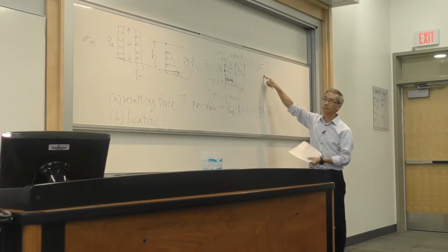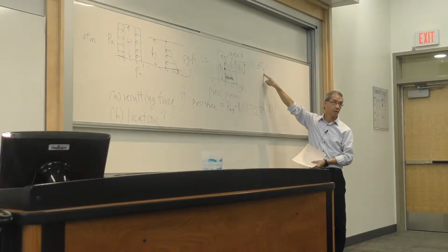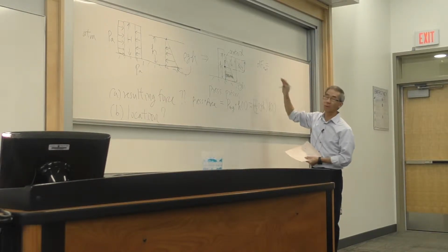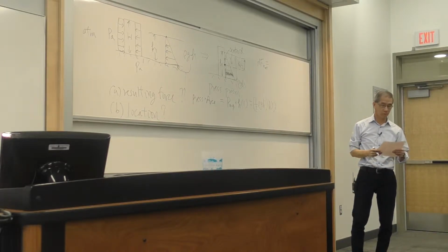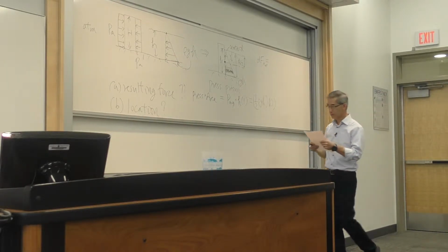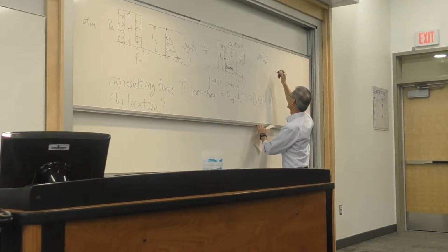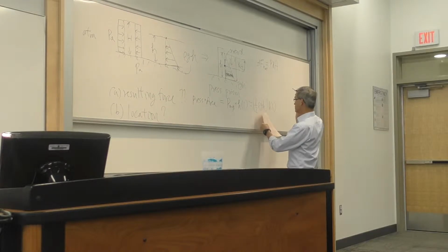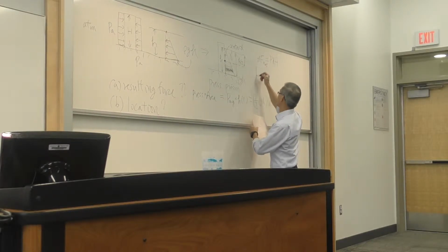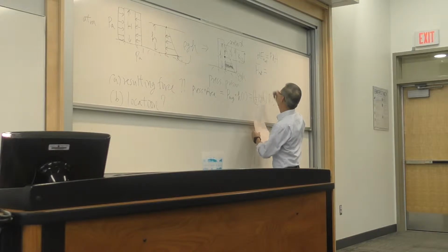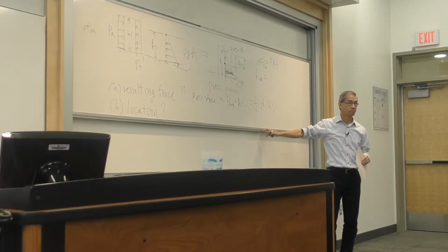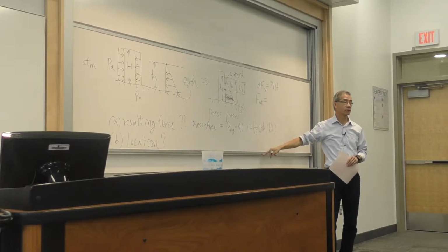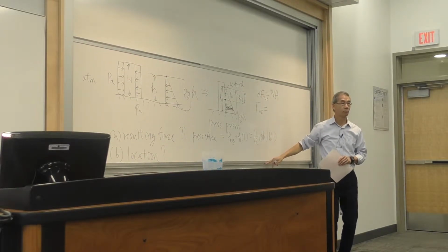The N stands for anyone? N stands for what? Net, meaning I'm not interested in the absolute pressure, but the gauge pressure, because ambient 14.7 cancel on both sides. Pressure times dA, and to get the total force, what do you have to do? You have to integrate, like we did with non-uniform velocity for continuity and momentum.